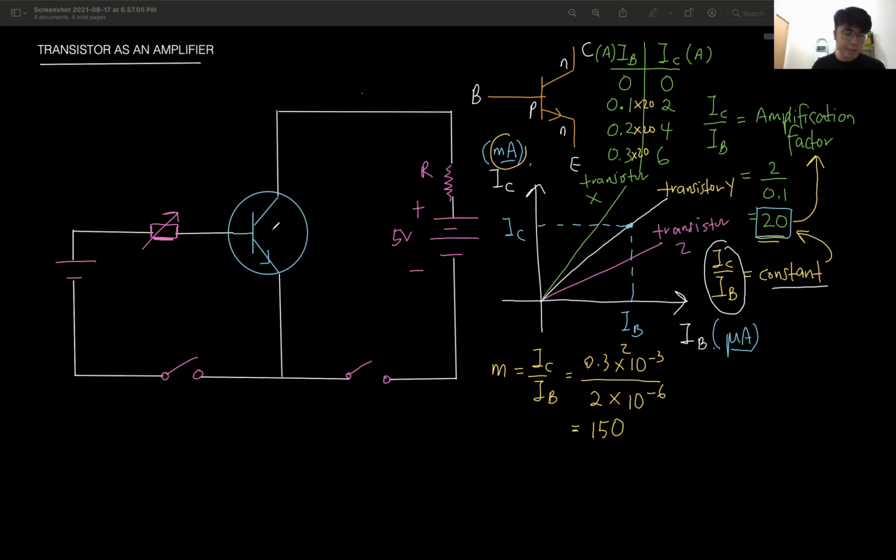Now, first we look at the type of the transistor. Now this one is a common, right? This line is being shared by two circuits. So this must be the emitter. This is the emitter. That is the base. This is the collector. PN. So this is NPN.